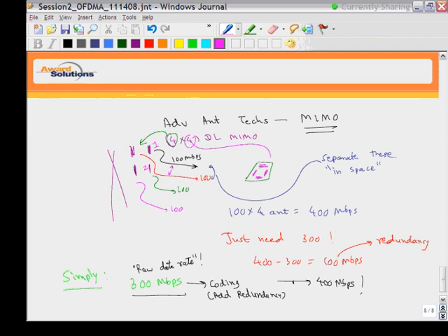Signal 2 is changed by the radio environment, but the environment will change those signals in a different fashion. For example, there will not be any phase shift on antenna 1 signal. Maybe antenna 2 signal is experiencing a 45-degree phase shift due to the radio environment. So we will do digital signal processing to figure out how the environment is changing the signals, and we will use that knowledge to recover the information coming from different antennas.